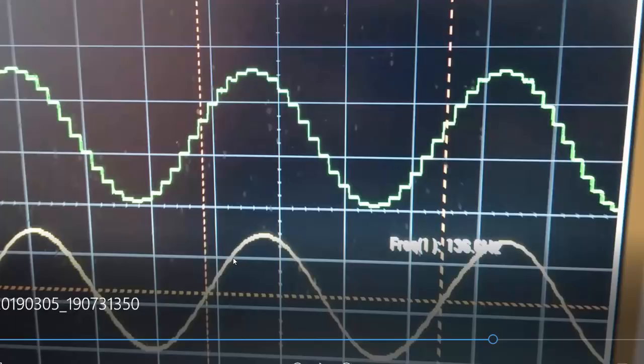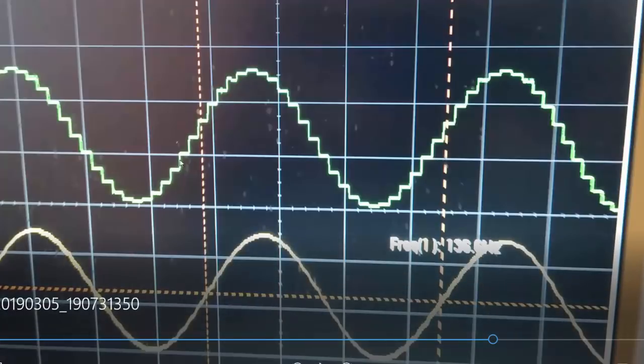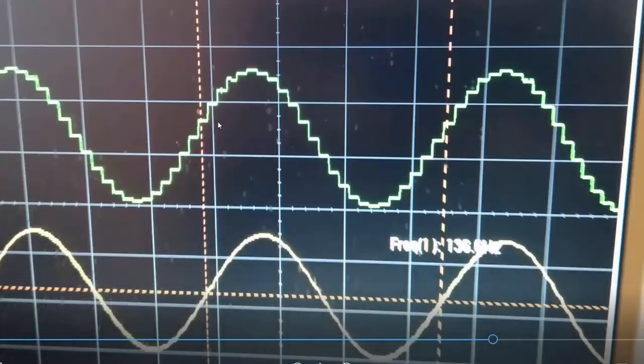And the reason I decided to put this here is if you've ever used a waveform generator or a function generator and you have one in your lab stock, this is what they do, right? They have a DAC creating the output signal, and then they'll have a filter which gives the signal a much smoother look. And a lot of them will have different types of filters to choose from, or you can even look at the raw output. But anyway, that's how a lot of waveform generators work.